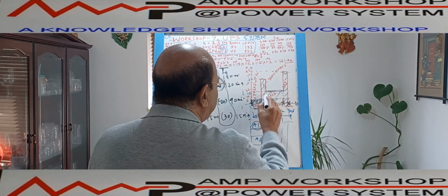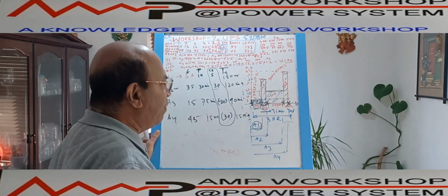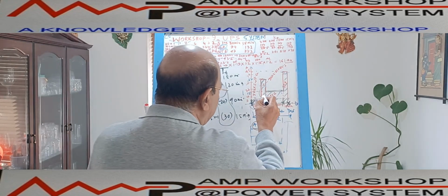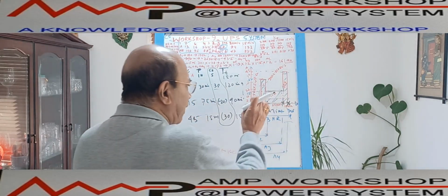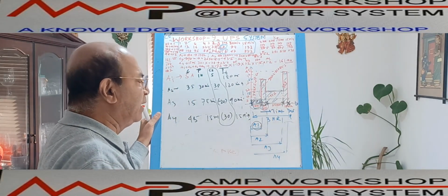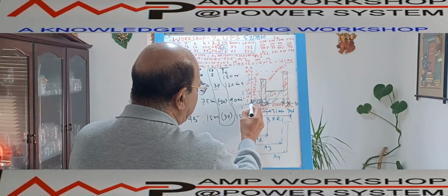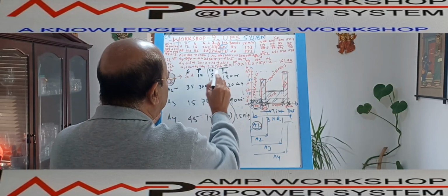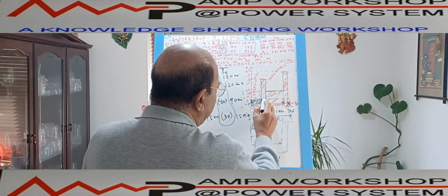Over that we are putting differential load. For that differential load, we need to calculate how the battery will be discharging. That's why the differential load for each section we have to calculate. How will we calculate that for a particular section? It is the maximum current of that section minus the previous current. So the first current is 5 ampere, previously no current was there, so the change of current is 5 and the total current is also 5.